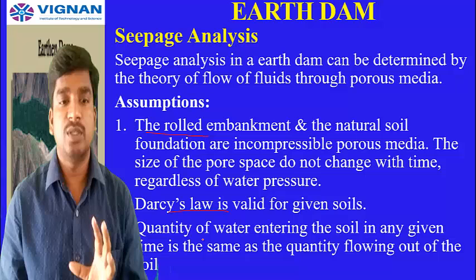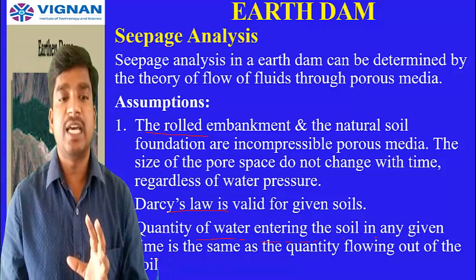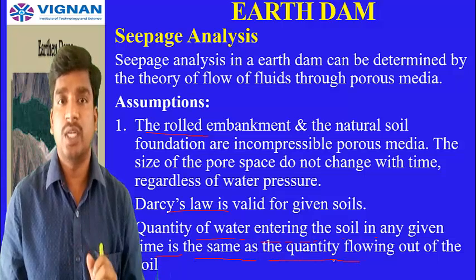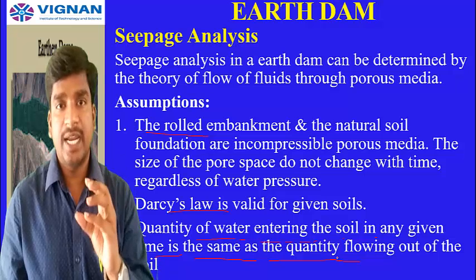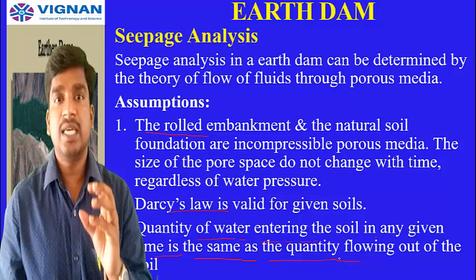That is the third assumption. The quantity of water entering the soil in a given time is the same as the quantity flowing out of the soil. Water entering the soil as well as water going out of the soil is a continuous system.